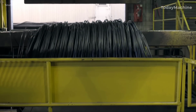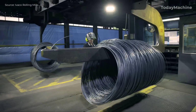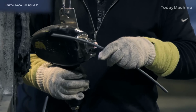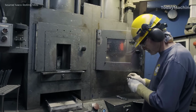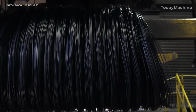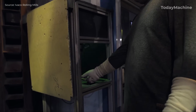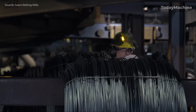Inspection and quality control. After the cooling process, the coiled wire rod is collected and subjected to rigorous inspection. Each coil is checked for grade, diameter, ovality, surface defects, and mechanical properties. If required, the coil may also undergo tensile strength testing. The final coil is then trimmed, shaped, tested, compacted, weighed, and tagged according to industry standards.